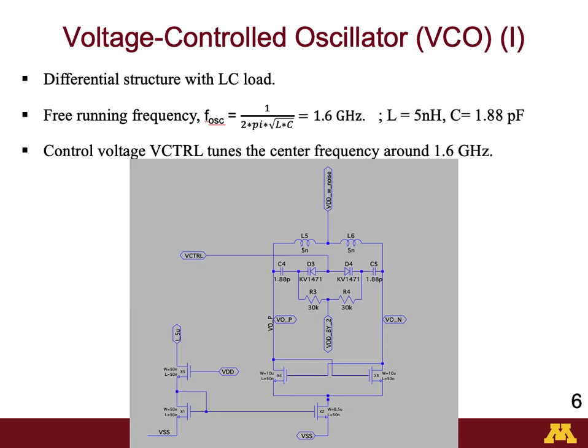Following the charge pump, the next block of significant importance is the voltage controlled oscillator. The main reason we are charging up or discharging down the load capacitor is to create a voltage on it, which in turn will be used to control this voltage controlled oscillator, the VCO.